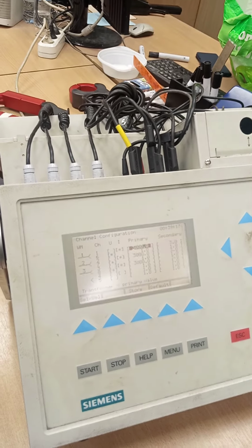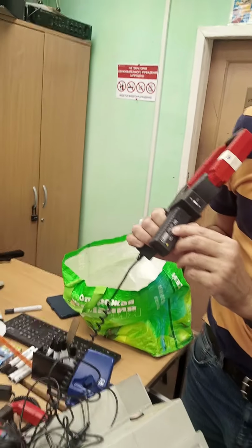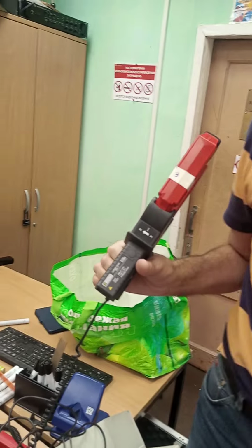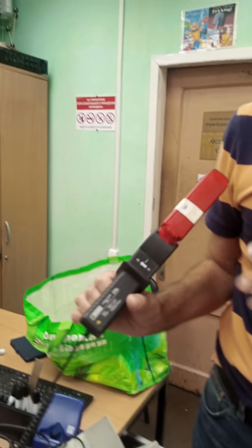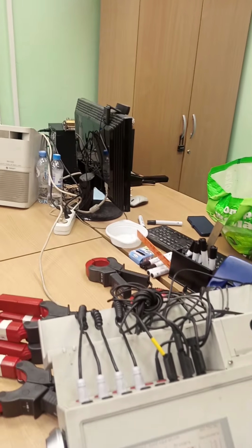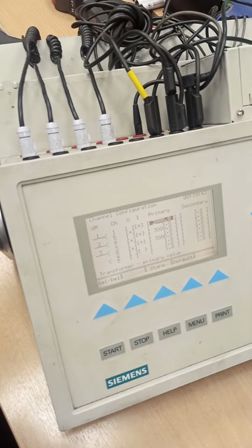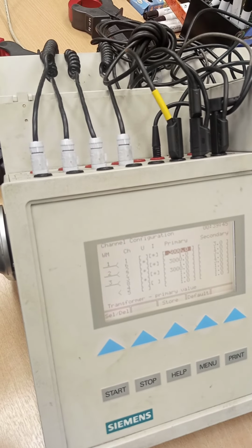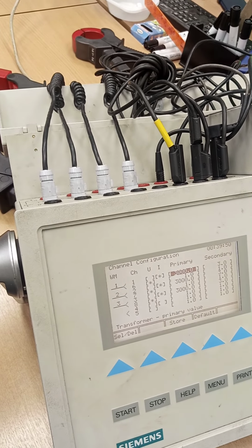Transformer ratio. For every clamp we need to enter its transformer ratio. But for these very high current clamps, the transformer ratio is equal. They all have the same ratio, 3000 to 3. So somebody entered it before us. So it's very simple. For smaller clamps,